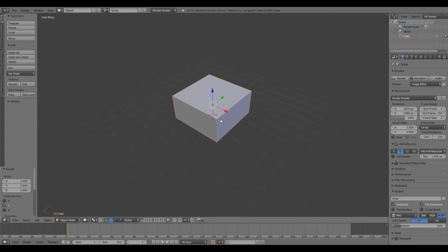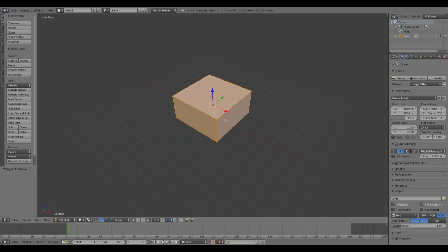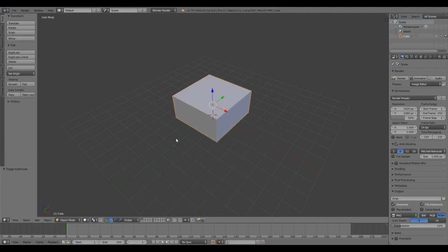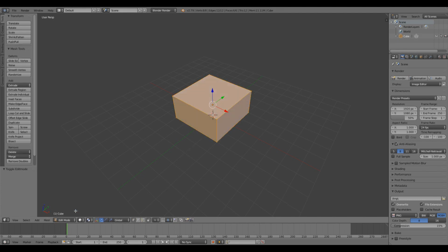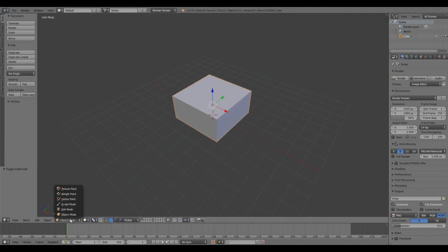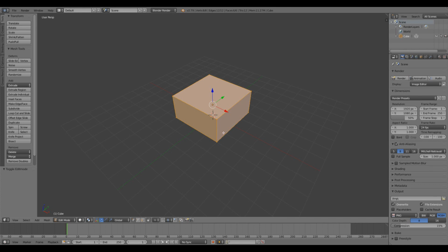OK. Now I want to create an L shape, so I hit Control, no, not Control Tab. Okay, with the Tab key I switch between Object Mode and Edit Mode. This is a shortcut key which I already learned. So I'm now in Edit Mode, and with A I can select all and deselect all. With Control Tab I can choose what I want to select, vertex, edge or face. I want to select face and I want to select this one.